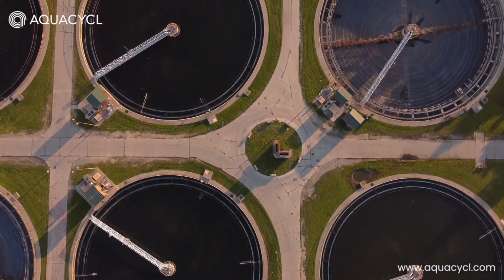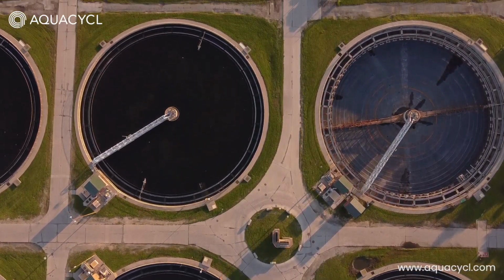So typically what happens is that it's going to go into a settling tank, and you settle out the sludge. You may have to add some flocculant, additional polymer to clump it up. Then you have to dewater it because you don't want to haul off a bunch of water. So you try to extract as much water out of the sludge as you can, and that can be done by a number of different processes. Then you take that still fairly wet bunch of solids and you haul that somewhere. Usually that will go to a landfill, but it's going to ultimately get applied to soil and that breaks down, and then that generates greenhouse gases as that breakdown occurs.